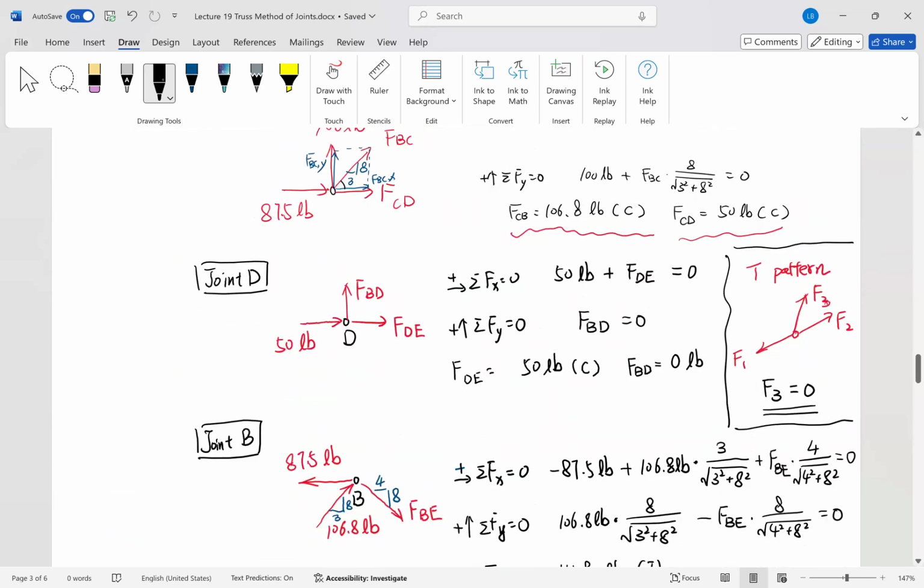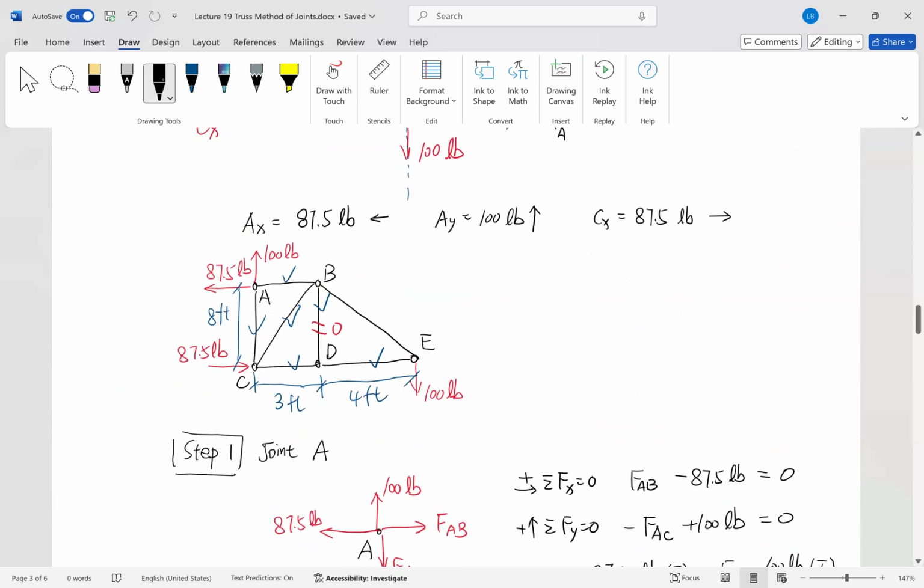And particularly, which joint you should solve first and which joint afterward, that is a strategy. I would like to encourage you to imagine that you're playing a battle strategy game, and your weapons here are the two equations for each particle, and you can take the unknowns as the enemies. So the rule here is to always ensure that the number of equations, the number of weapons you have, is not less than the number of enemies, or the number of unknowns here.